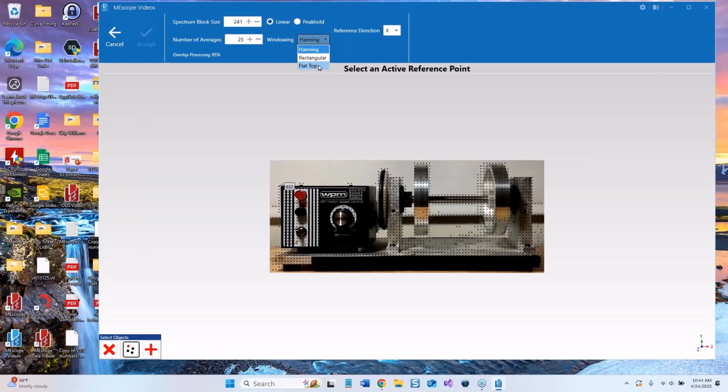Leakage is the term that happens. The energy leaks out of the peaks, the resonance peaks, if we're looking for mode shapes. And the Hanning window reduces that, so we can actually curve fit ODS-FRFs and get what are called operating mode shapes. So we can do all that. You can see here, again, a lot of the background was removed in the wizard. That's important.